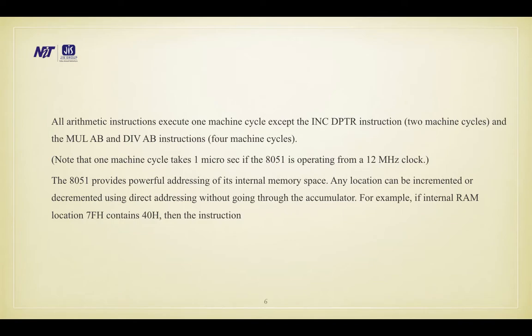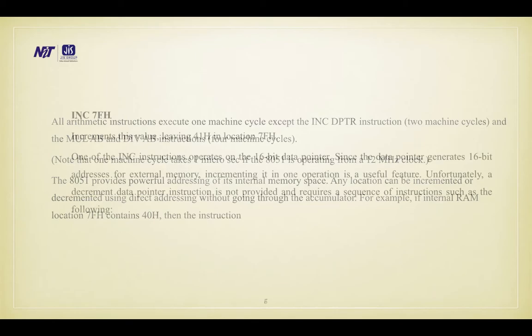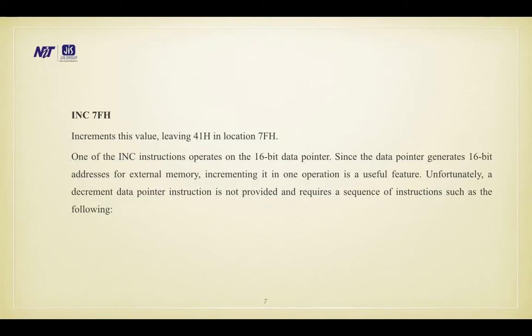The 8051 provides powerful addressing of its internal memory space. Any location can be incremented or decremented using direct addressing without going through the accumulator. For example, if internal RAM location 7FH contains 40H, then the instruction INC 7FH increments this value, leaving 41H in location 7FH.